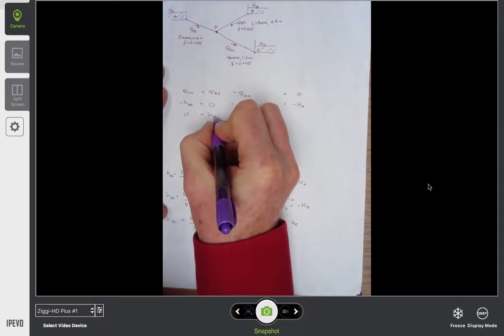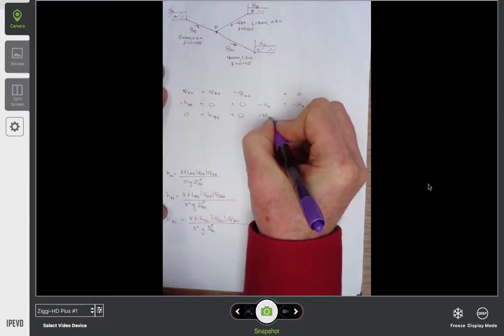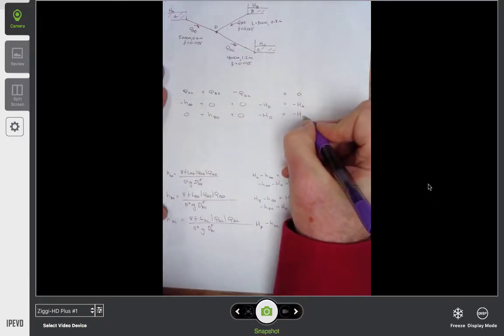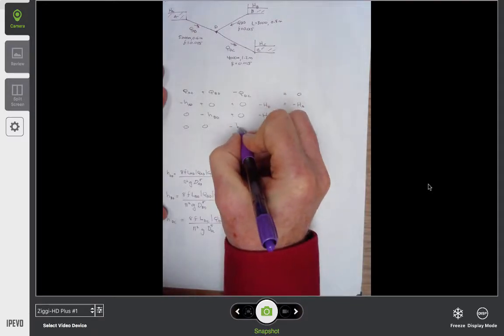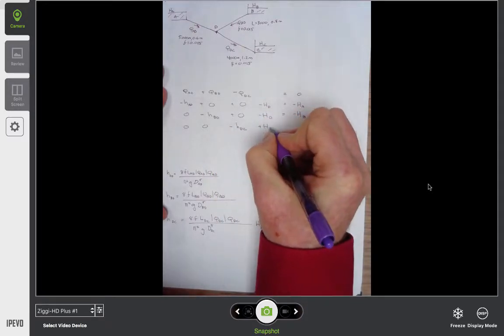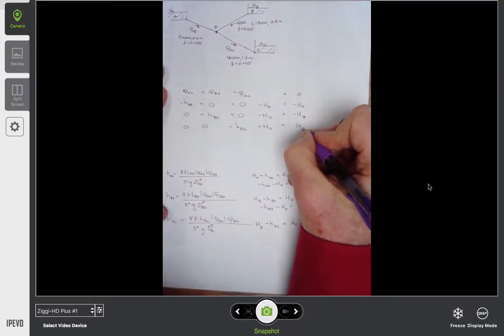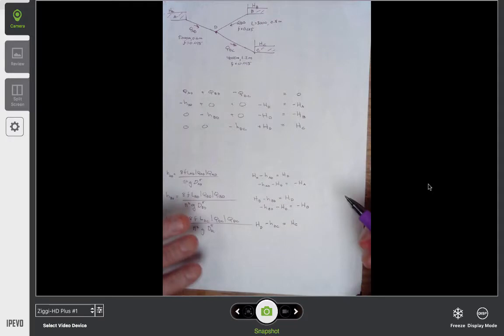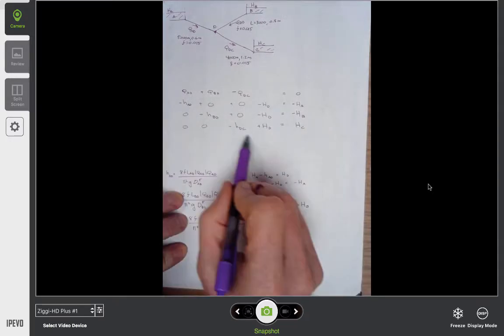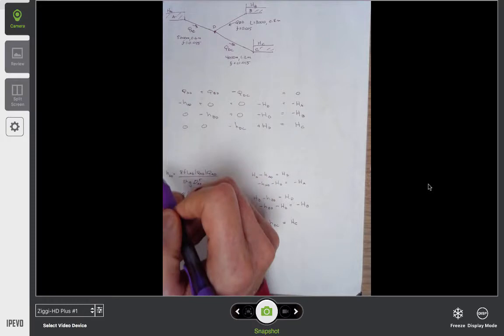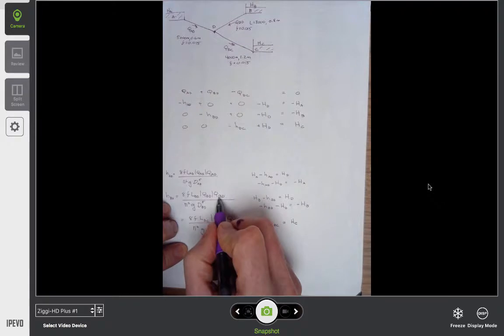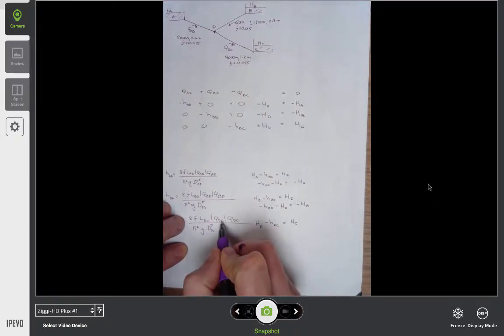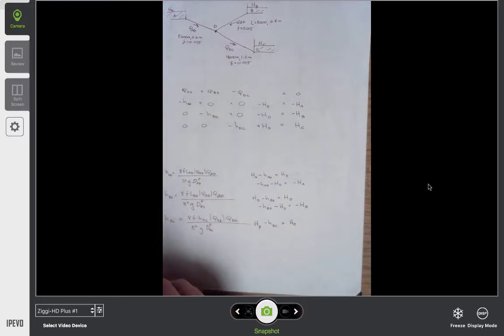Minus HBD minus HD equals minus HB, and lastly, minus HDC plus HD, slight sign change there, equals HC. Now those are my 4 equations and 4 unknowns, and you would think, wait a minute, those are 6 unknowns, but no. HAD depends on QAD. HBD depends on QBD, and HDC depends on QDC. So we'll take advantage of that observation.